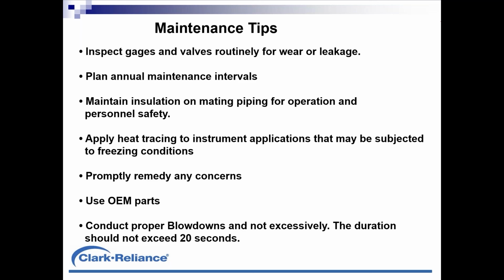When you conduct blowdowns, we recommend that they be done properly, not excessively. Clark-Reliance has a blowdown procedure that you can find on our website. The video on our website takes about 6 minutes to watch, but we recommend the procedure not taking more than about 20 seconds. You open a drain valve and watch for 20 seconds. It's plenty of time to see water drop out and a line clear, and if you're blowing steam out the drain.